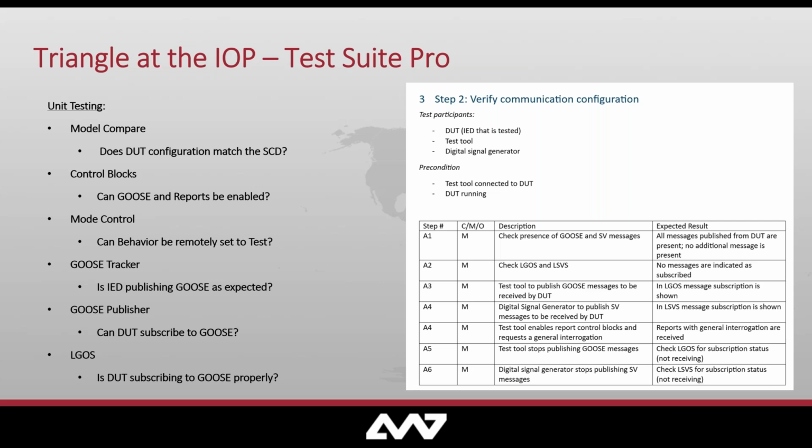We could use the GOOSE tracker to make sure that the device was in fact publishing GOOSE as expected, and then we could publish our own GOOSE using Test Suite Pro that the particular device under test was configured to subscribe to. And then we could take a peek at the LGOS logical node. If you're not familiar, LGOS in 61850 is a logical node on an IED that can tell you if it is in fact receiving the GOOSE stream that it's subscribed to.